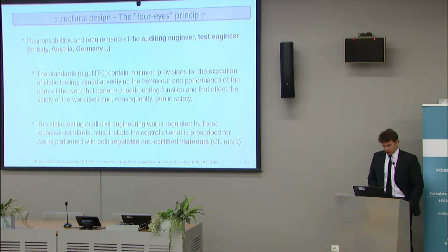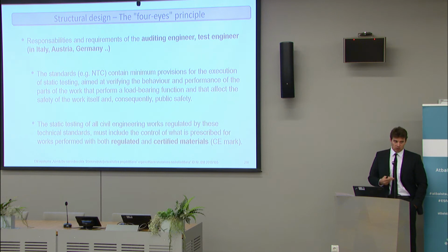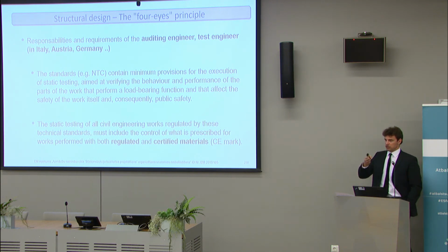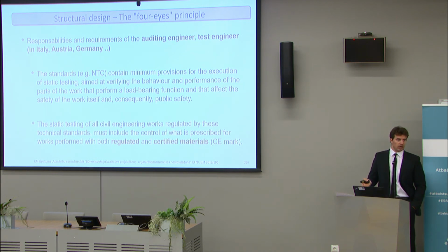So in Italy at least, the ingegnere collaudatore, this external reviewer, not only checks the calculations, not only visits and supervises the building when it is finished and functional, but also has to certify that all materials used in the construction were certified, that they had a CE mark, for example.